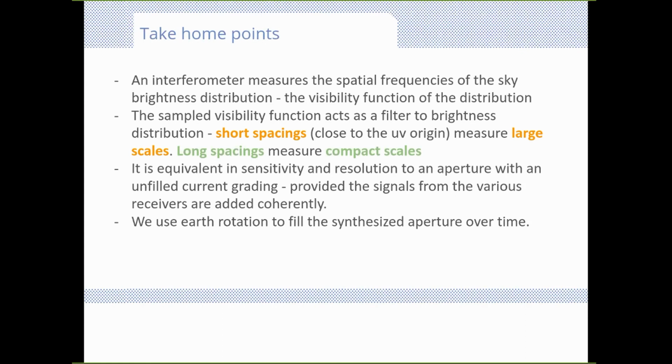It is equivalent in sensitivity and resolution to an aperture with an unfilled grating, right? So we can have either a single very large dish with holes in it. That is going to be exactly the same as having an interferometer between spacings physically separated, right? So we've made this relationship. This is provided that the signals from the orthogonal wavefront can be added coherently, right? This is the golden rule. We have to be able to add signals coherently.